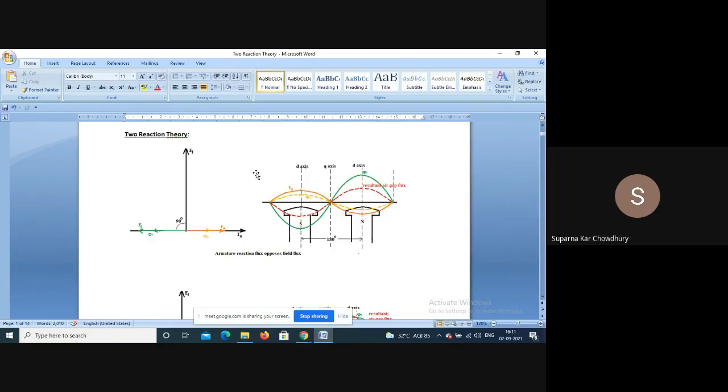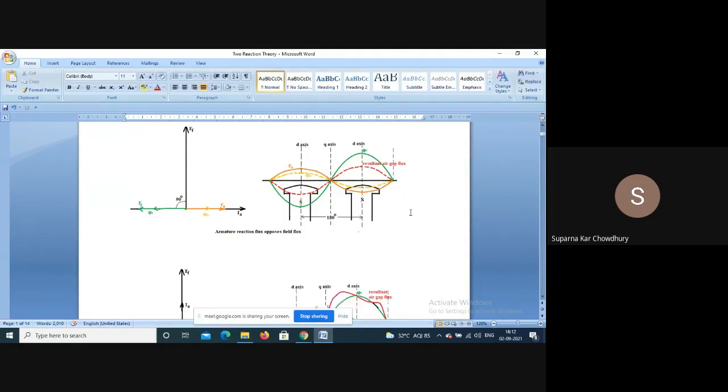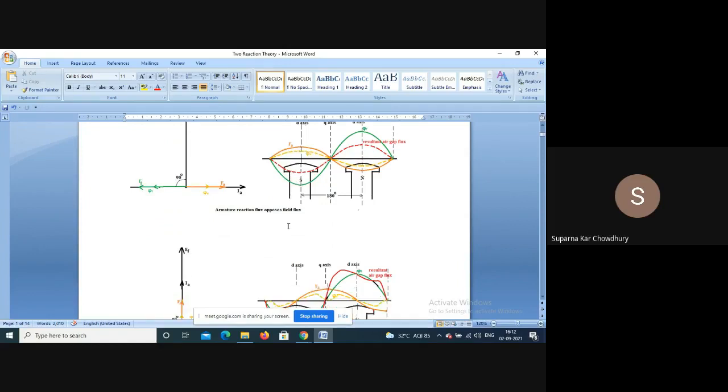This will be your FA. Now the flux is maximum in this polar region. In the polar region the air gap is small, and only here the air gap is large. So except in this region, the flux will approximately follow the MMF wave. So it is approximately a sine wave. Now this is for lagging current. If we have a 90-degree leading current, the same thing will happen, except the flux will be magnetizing in nature here instead of demagnetizing.